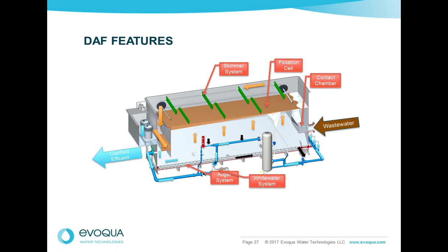Now, once the solids have settled and the solids have floated, hopefully more floating than settling, there has to be a means of separating that clarified effluent from those solids, and there's a baffle system within the DAF that carries the flow around through an effluent weir system, and then for discharge of the clarified effluent for direct discharge or further treatment downstream.